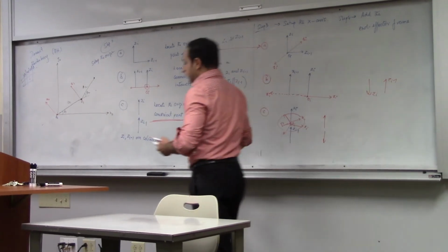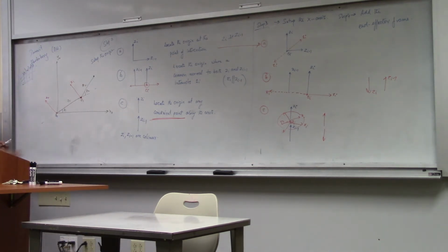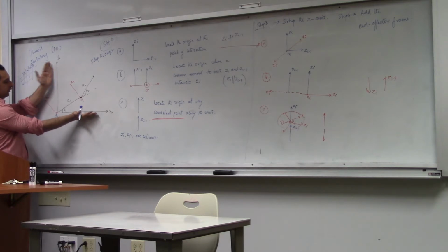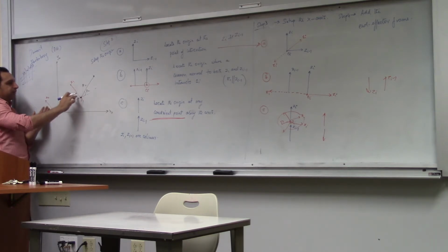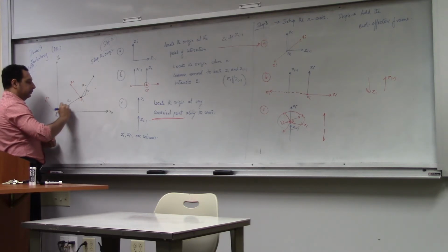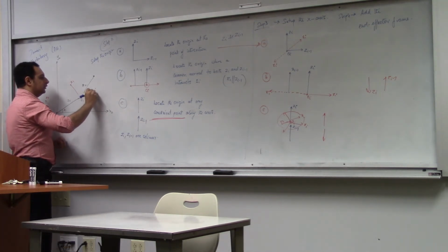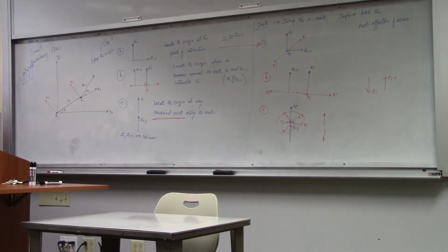Okay, so for the end effector frame, what I'll do is I'll just replicate this, but let's finish drawing the x in this case. So here if you look, the first origin is fixed. This is the global frame of reference, x0 and y0. Now I have to draw the x here. In this case, these two are perpendicular, so I'll draw x along a line that is perpendicular to both, a common normal. A common normal is like this, so this will be x1.